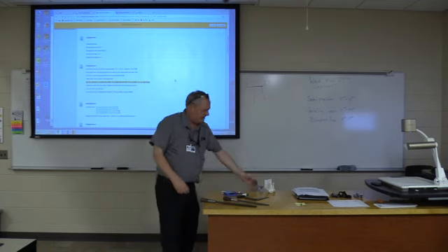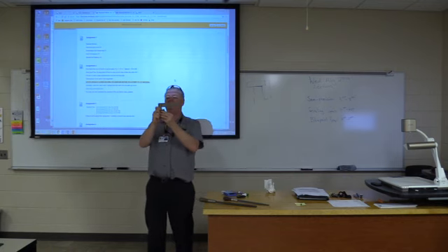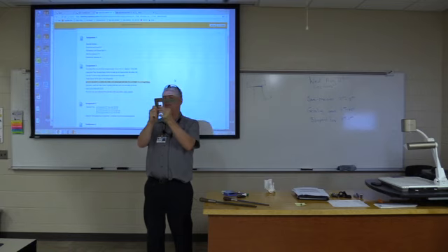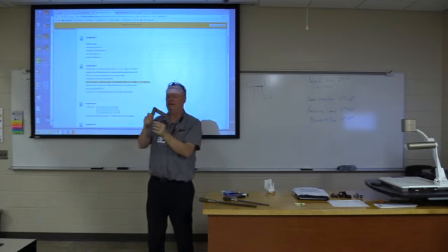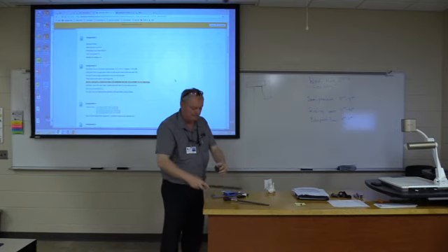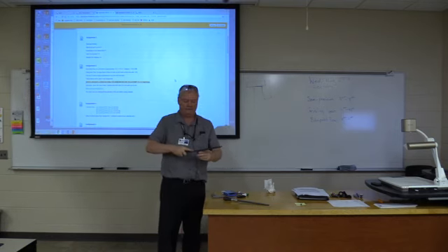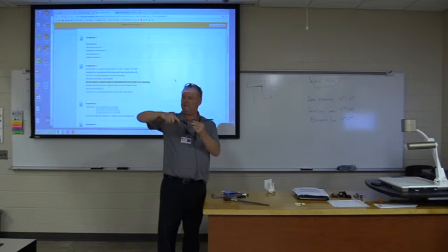So as I take this, put my large, longer face that I just filed nice and flat up against the back of the machinist square, and I look down, I see that this has a high spot here, and it kind of is like that. So this goes back into the vise, and it's a matter of squaring it off, holding your file square and flat, taking the high side down to make this perpendicular to that.